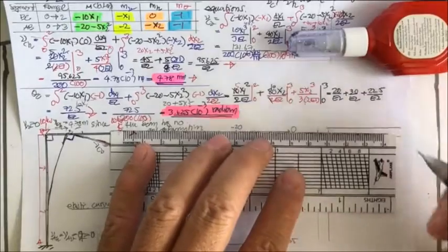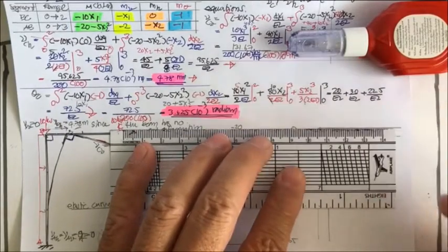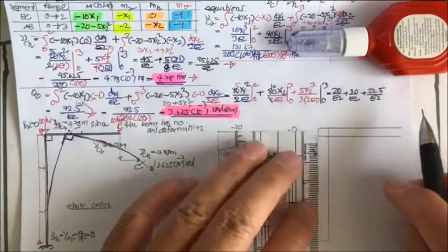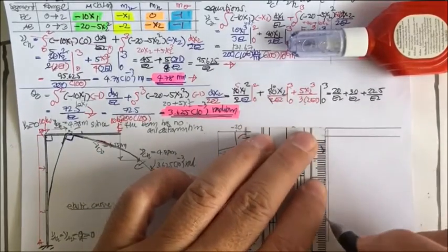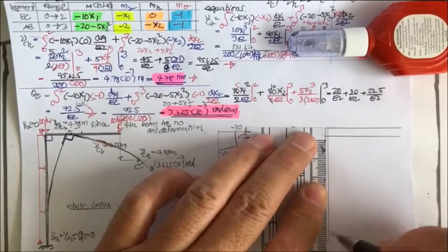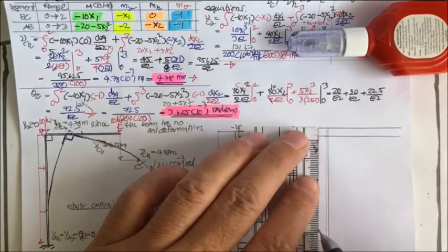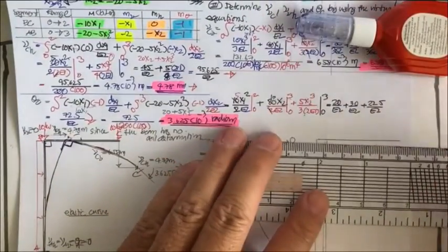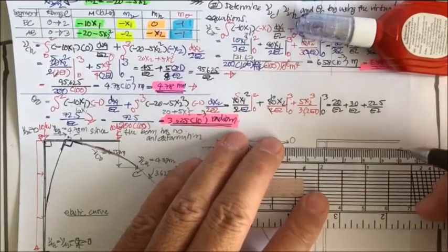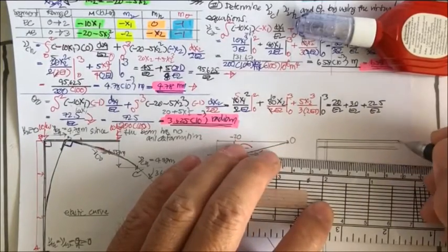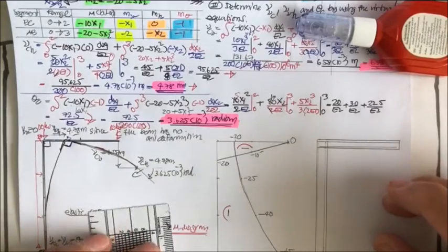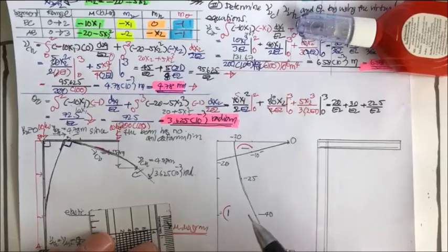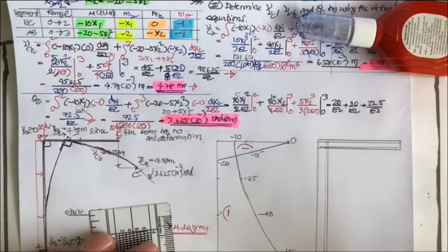And what we have, if this one is a reinforced concrete beam, you also can use the moment diagram and elastic curve to find the pattern of the reinforcement. Usually we have reinforcement like this for the beam, but for the frame, when subjected to moment like this, we always put the reinforcement on the tension portion.